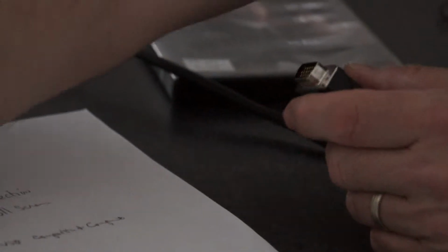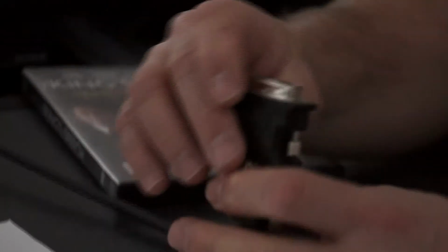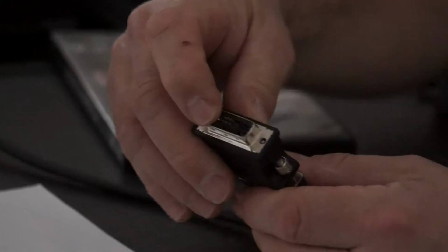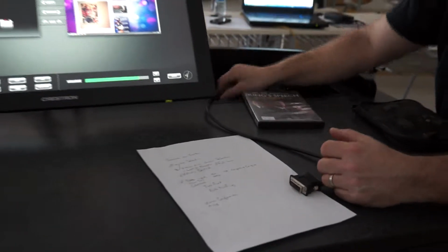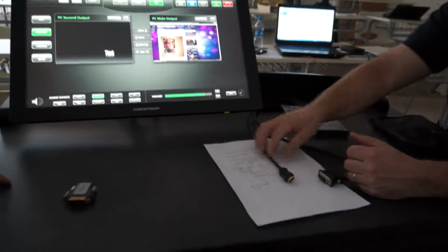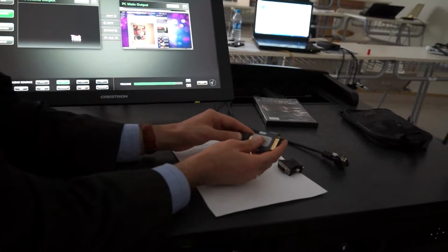So literally, when I do that, it's passing those pairs over to those 4 pins plus a couple more that are right around that notch or that slotted one. On the digital side, we don't need those connectors because it's using all the others, and it's just a pin-for-pin mount to the HDMI. If my memory is correct, there's 19 pins on the digital HDMI connection.